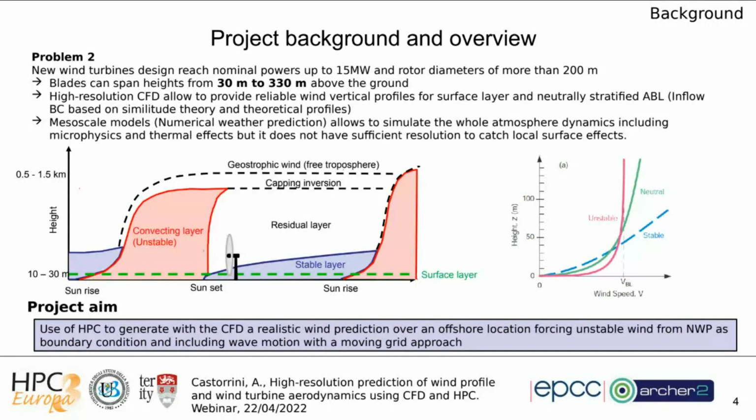Now, for this inflow condition of the wind, there are many models that can be used to generate or predict it. But basically, when you rely on theoretical or classical CFD modeling, these standard models do not capture effects that are connected with the entire atmospheric boundary layer dynamics and also the cycles of thermal stratification that change